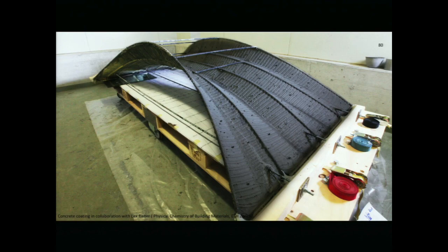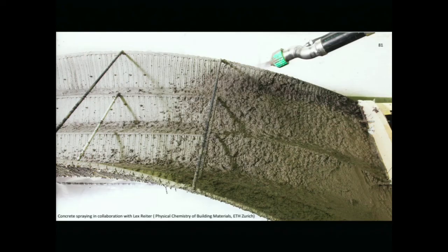After this has hardened, the next layer is set up, and it is just a 5mm layer which will form the stay-in-place formwork. The entire formwork weighs about 20 kilograms, so it is very light and very easy to transport, after which one can pour the concrete in a traditional manner.